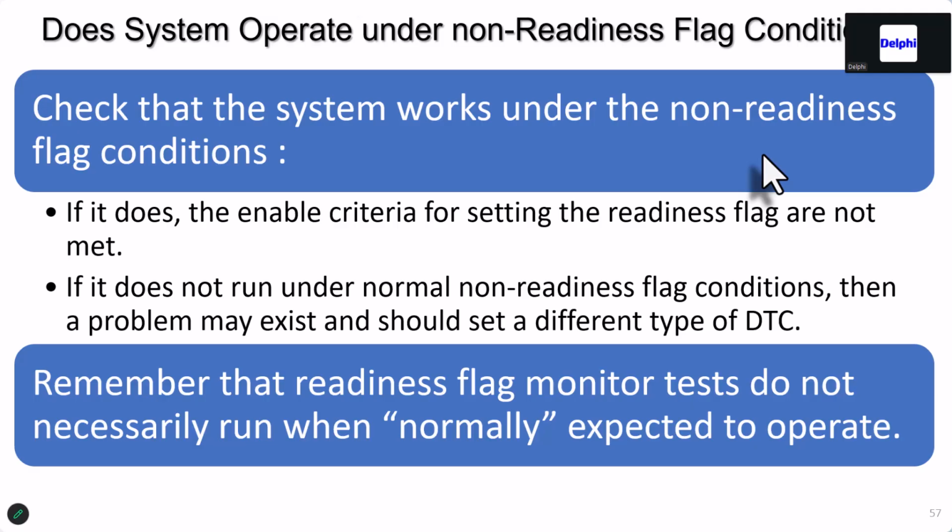And the FTP is a reporting component. If you take away anything from this class, always ask yourself, what is the reporting component for that particular monitor? And in EVAP, it's the FTP. We know for the cat, it's the O2s, front and rear, air fuel sensor, oxygen sensor, could be air fuel and air fuel if it's a Toyota. But those are the reporting components. If they're not working right, then you may not be able to run the test. So you got to run the verification to make sure that they're working to a point. So I call this non-readiness.